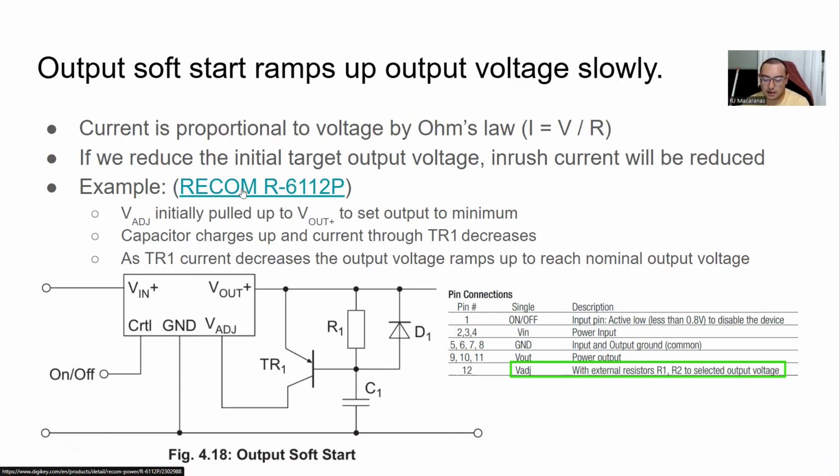And so really this is very specific to this device. I've implemented soft start in digital control, and it's a little bit easier because you're basically just incrementing a variable that represents the output voltage. But here, you really need to pay attention to how your circuit works and how you can implement this soft start ramp. Typically, the reference voltage is hidden within the controller IC, but you do have a way of adjusting the feedback network to slowly ramp up the output voltage, I think. But it's something to consider, right?